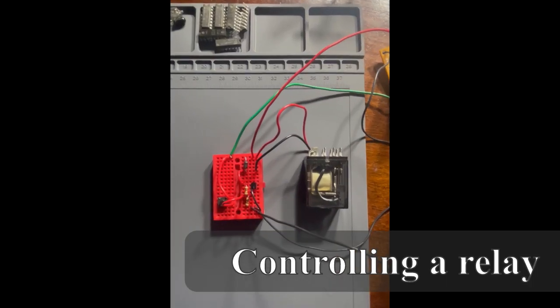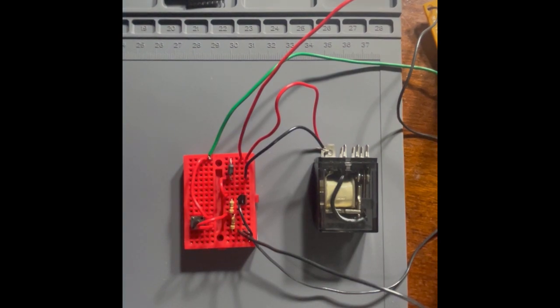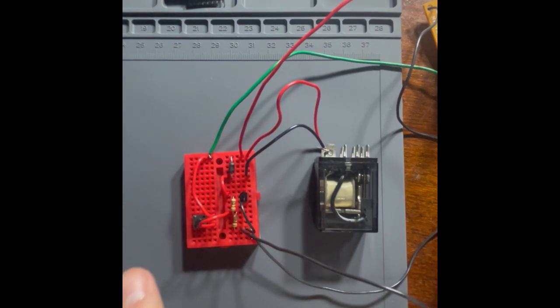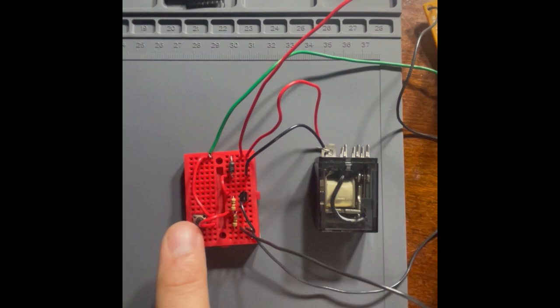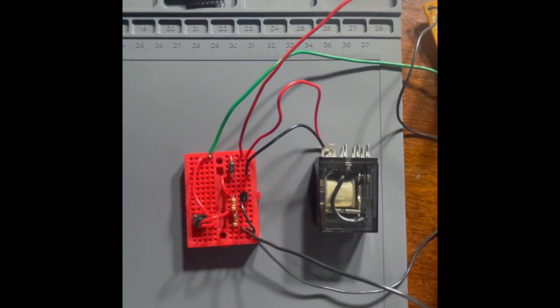Now here is a relay being controlled with a switch. As the switch is pressed, you can see the mechanical arm in the relay opening and closing. Relays are often used in thermostats, vehicles, automation equipment, and other various devices. This relay requires 12 volts and consumes 76 milliamps of current. The relay is activated using 5 volts and only 1 milliamp of current by using the transistor and the switch.